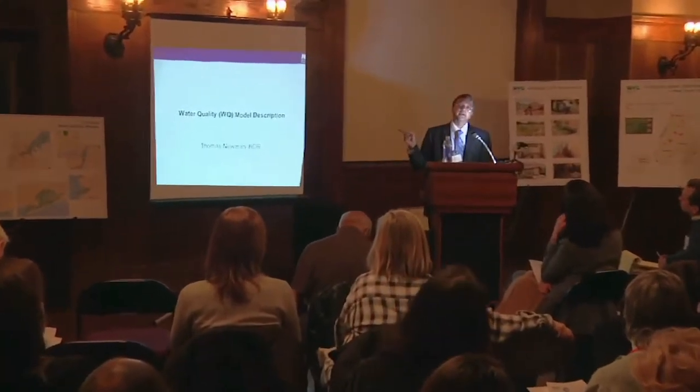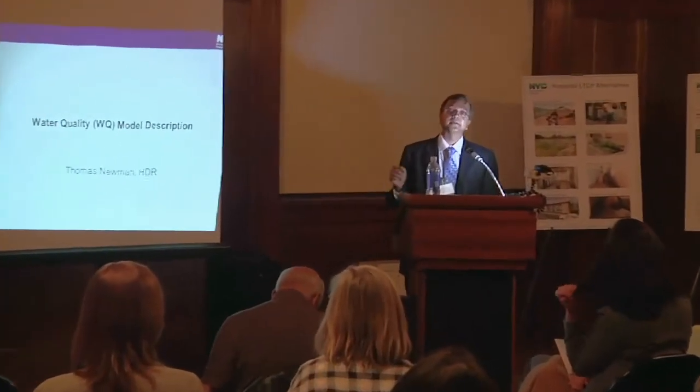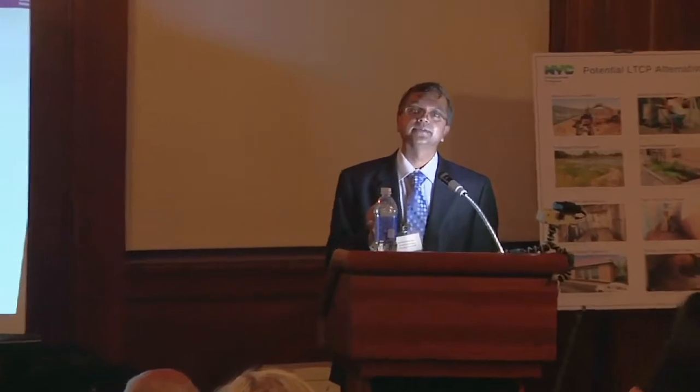For the storms that were captured during the calibration process, that's one of the key things you need to recognize. You don't just put the meters in, and once you get two storms, take the meters out. You start looking at the characteristics of individual storms. Do we have smaller storms that represent the initial losses in the system, like infiltration and filling up the potholes, before the runoff gets generated?